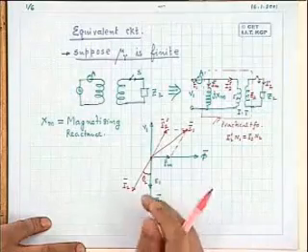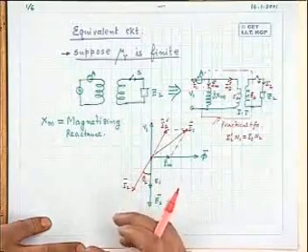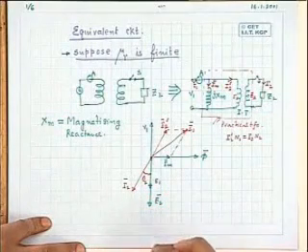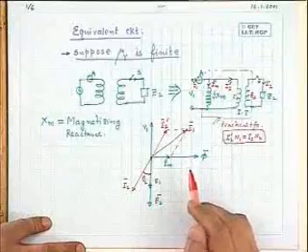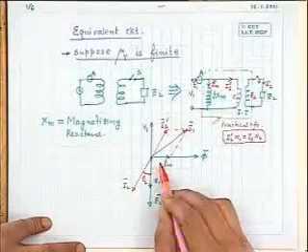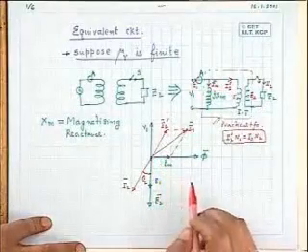So for all practical calculations, or say in the laboratory for testing purposes, you forget about that small change in current when deciding the ratings of the ammeters to be connected to carry out a particular test. But this is true: I2 dashed N1 is equal to I2 N2, and I1 N1 is close to I2 N2, very close to I2 N2, because Im itself is quite small.